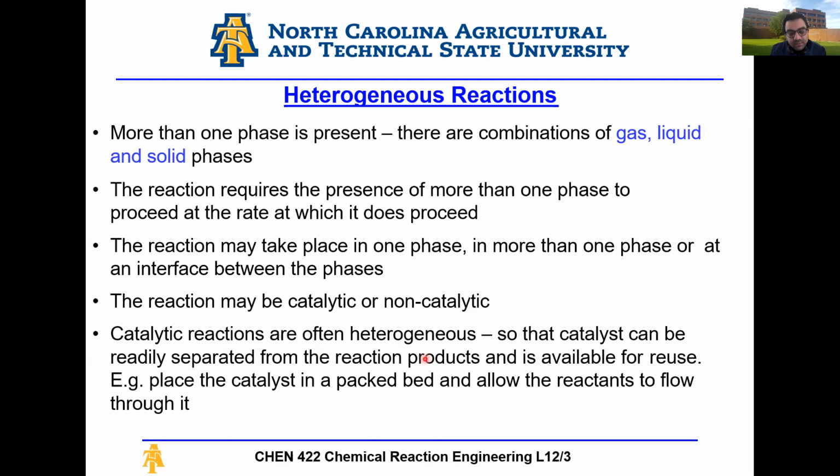It's a multi-phase system, and the catalyst is usually separated from the products and recycled back. So if I have a gas-liquid system or gas-solid system, my solid is the catalyst, my gases are the reactants. So I'm reacting A and B on a catalyst surface, and then I get a product C. If C is in the liquid phase, for example, I then take the liquid product with the catalyst, separate the solid catalyst and recycle it back to the process. And then I have a clean stream of liquid.